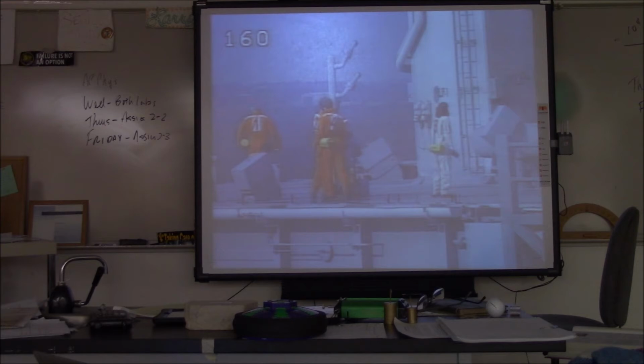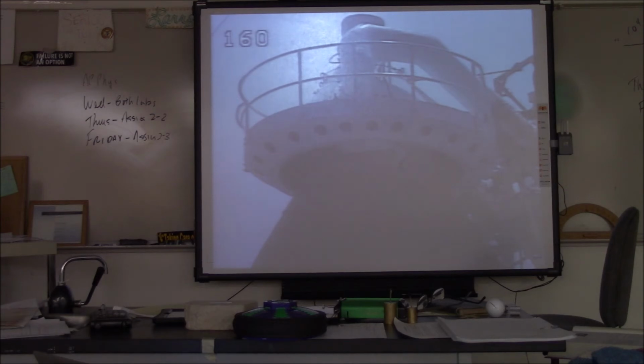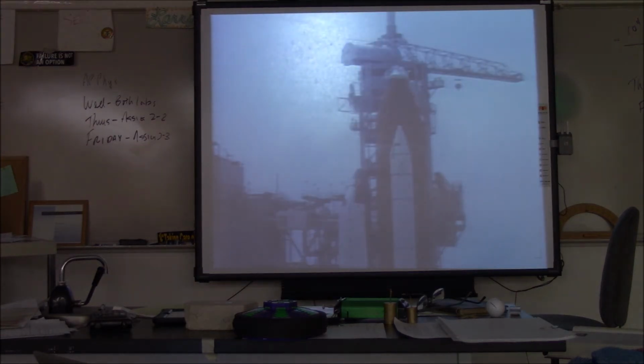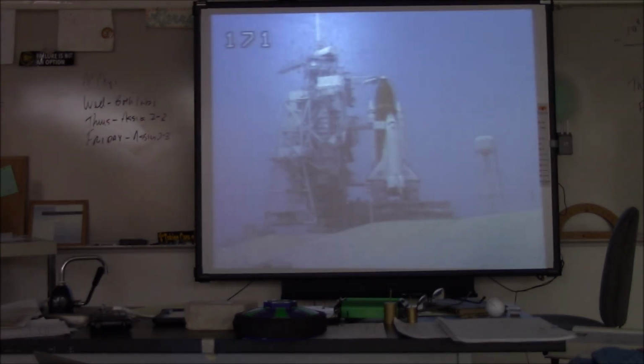The filling of the liquid oxygen and liquid hydrogen tanks occurs on the launch pad several hours before launch. The oxygen vent arm, which caps the top of the external tank, allows vaporized oxygen to escape from the tank, and thus prevents the tank pressure from building up to excessive levels. A similar arm allows the lower positioned hydrogen tank to also be vented.